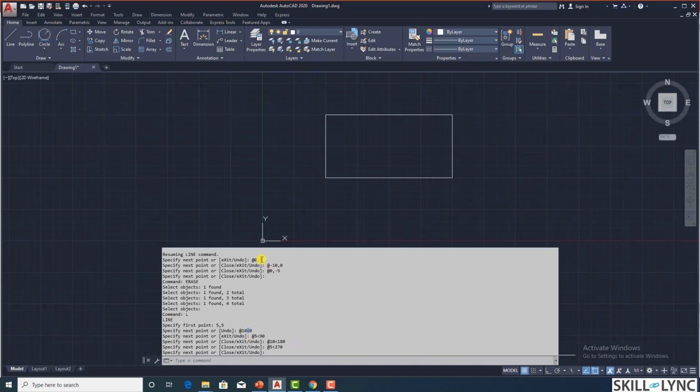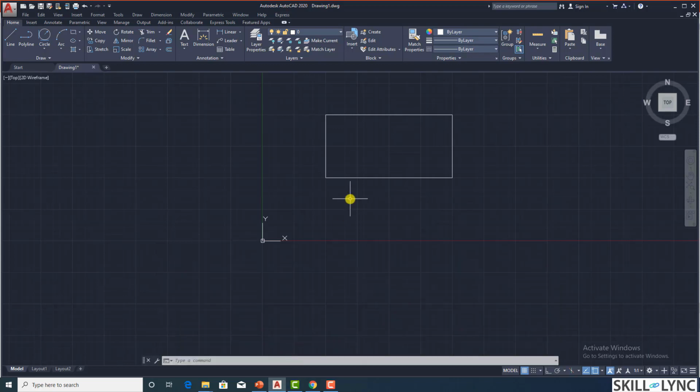Earlier you had to again specify in the relative rectangular system, calculating the incremental distance whether in the x or in the y. But in polar coordinates you just have to specify the incremental distance irrespective of the direction. The direction is taken care of by the angle. Okay, so this is the relative polar coordinate system.